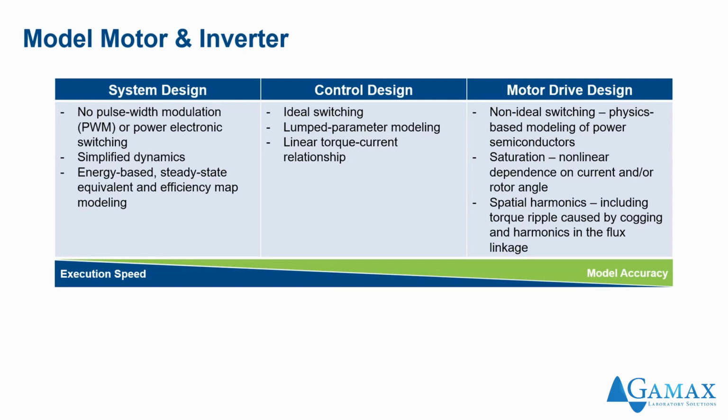But in some applications, we will want to model the saturation and the spatial harmonics. We can do that with the use of Simscape Electrical. So system engineers often rely on more abstract motor modeling that balances mechanical and electrical power to accelerate motor simulation and analyze system-level performance of a motor drive.